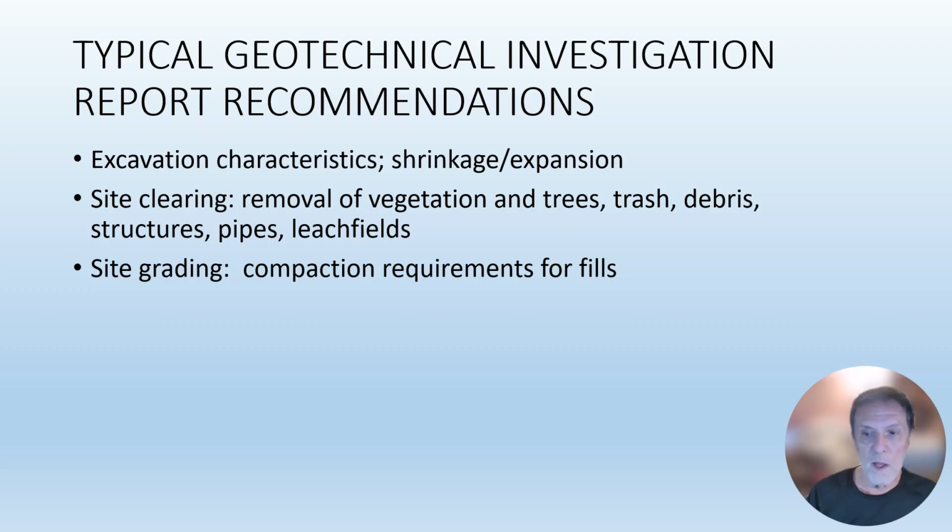So you've got to deal with the quantities of earth, whether you need to import or export materials. If the material expands when it's put back in, like you have solid rock and it's broken up into pieces, now the volume is expanded. So the question is, where do you put the excess rock? Okay, that figures in, not everywhere, but on certain sites. Of course, you have to remove trees, vegetation, trash, old structures, pipes, leach fields, all that has to go and be disposed of off-site. And during site grading, two basic operations, cutting and filling.